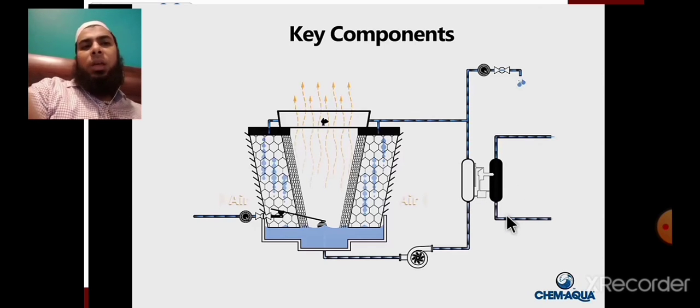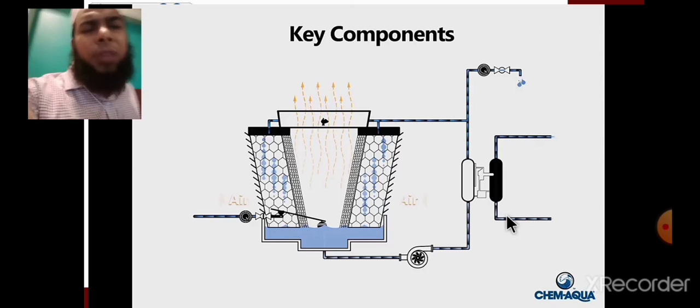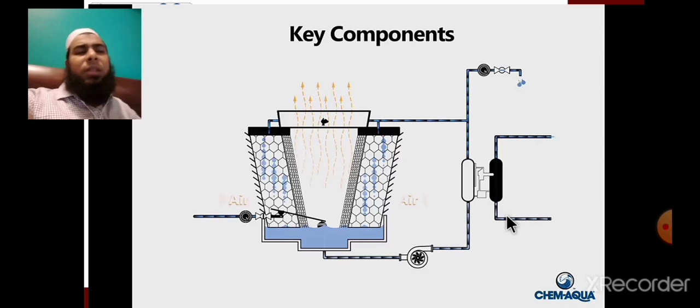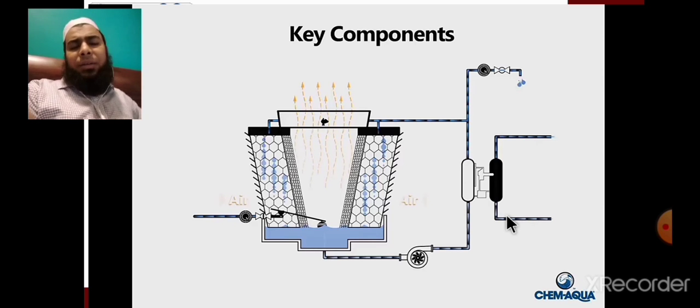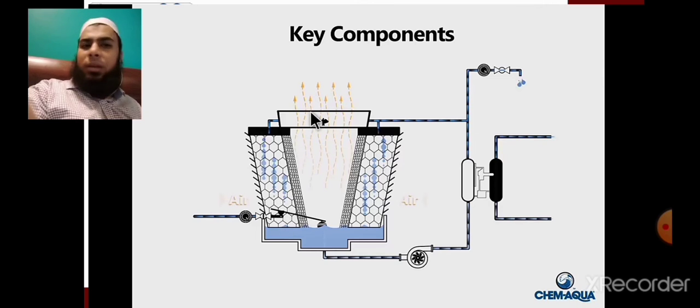In this way, the cooling tower circuit has very high efficiency if it is placed in dry places. But even if it is situated in Karachi, which has a humidity around 70 to 80 percent, still 30% of the air has the ability to absorb water. So even in such places, it rejects heat through the evaporation process too.